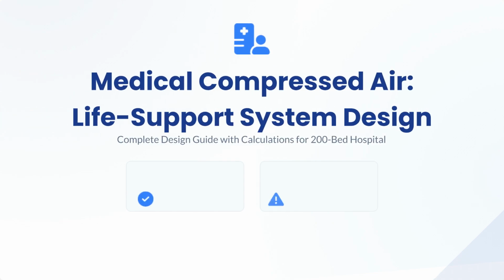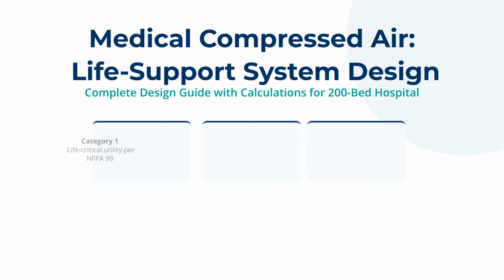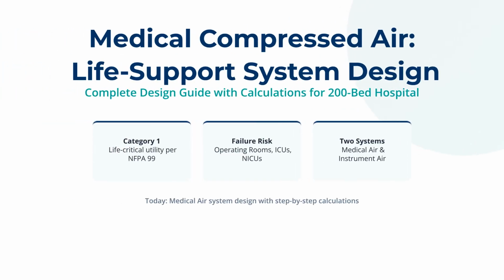This video is a complete design guide for medical compressed air systems, focusing on calculations for a 200-bed hospital. We'll cover both medical air for patients and instrument air for tools, which are life-critical utilities under NFPA 99 Category 1. We will focus on the medical air system design, with step-by-step calculations. These systems are Category 1, meaning failure poses significant risks, particularly in operating rooms, ICUs, and NICUs.